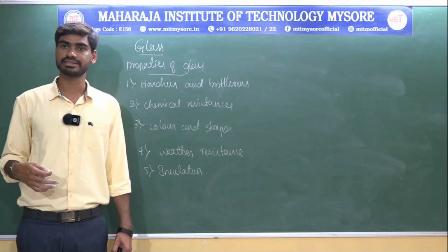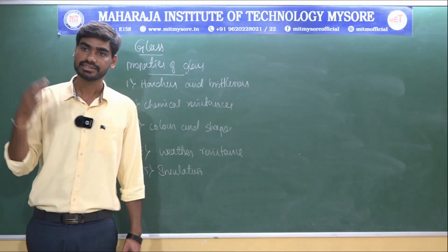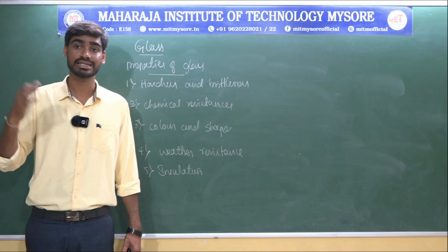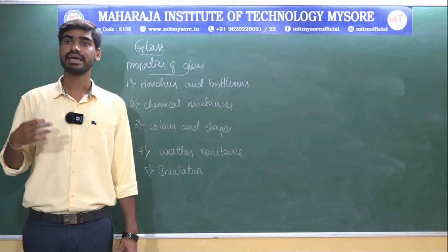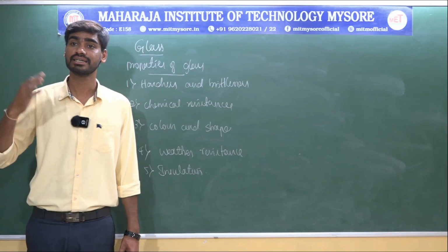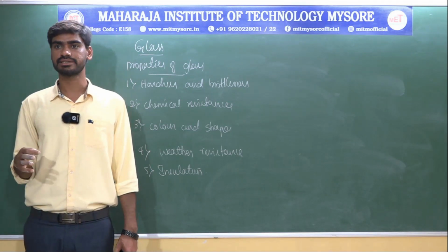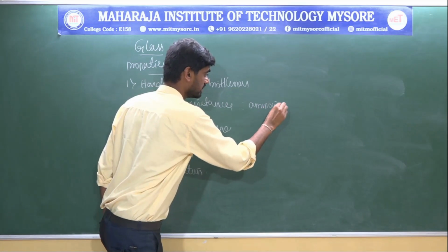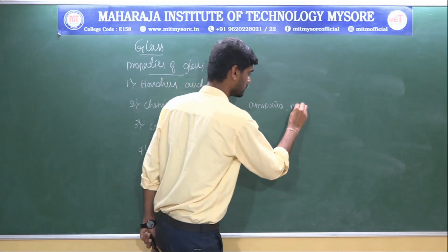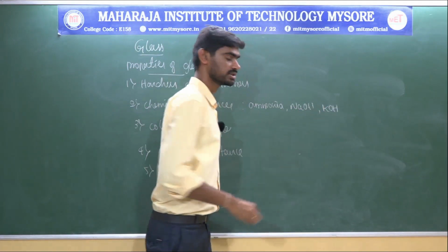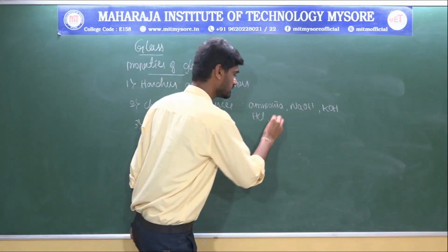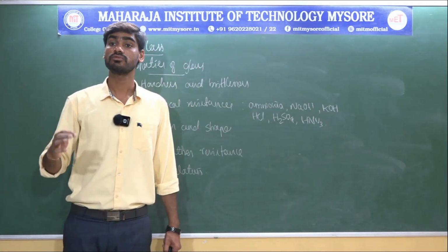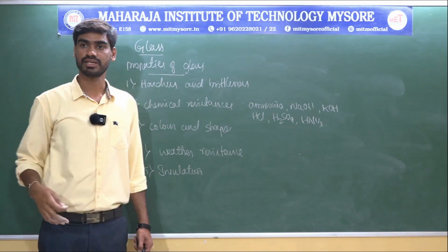When it comes to the second property, chemical resistance, glass can easily resist acidic impacts or the effects of chemical reactions that take place in various environmental conditions. Most substances, including solutions of inorganic alkalis like ammonia, bases like NaOH, sodium hydroxide, potassium hydroxide, KOH, and acids like hydrochloric acid, sulfuric acid, H2SO4, and nitric acid, HNO3, are very well tolerated by this type of glass.